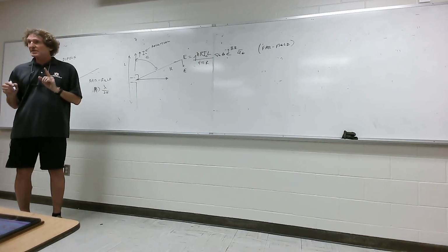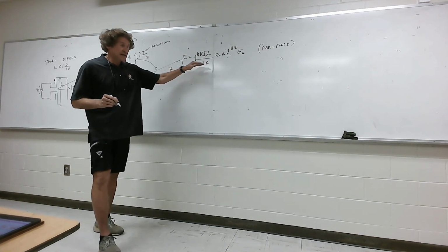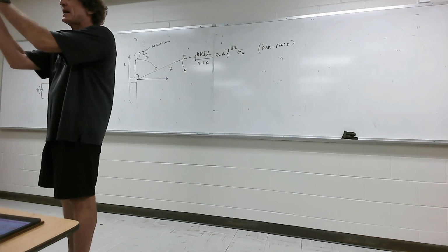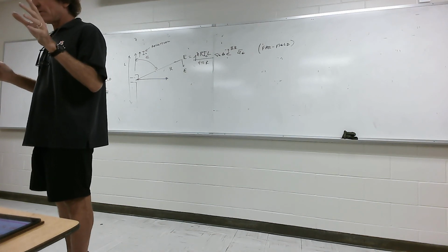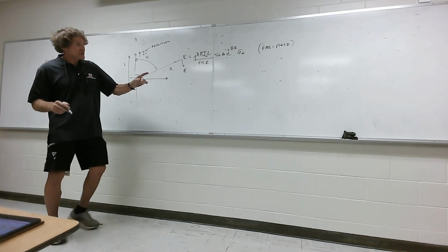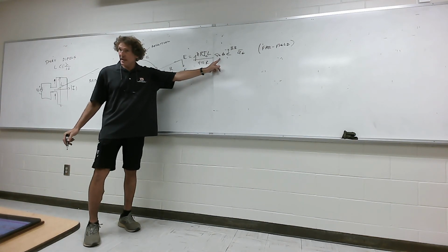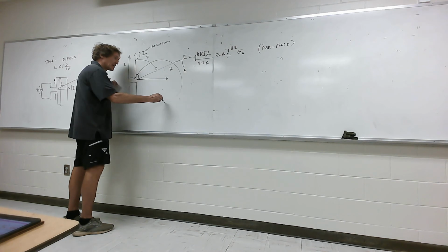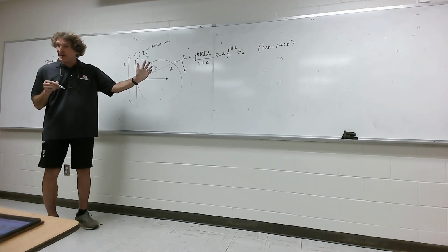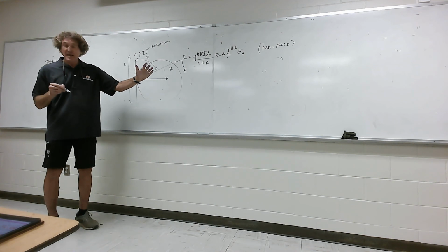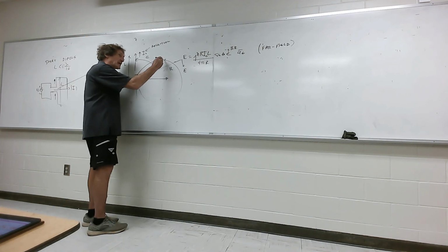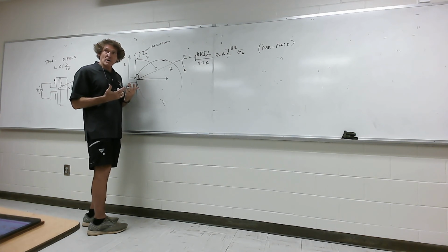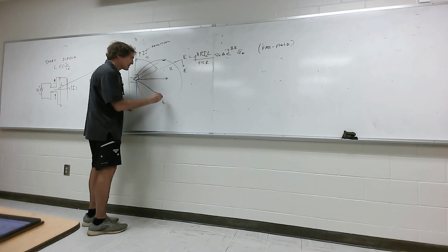Now, if you were to actually get the power density, how would I get the power density if this is a radiated field, anybody? One half the magnitude of that E field squared over eta. Y'all hear me? If I do that, you can see it's proportional to the sine squared, can't you? Just square that. Here's what it would actually look like. If I plotted that, this would be the power pattern. It'd be a sine squared pattern. Maximum value there. We'll get into this, but when we find where the half power points are, when the maximum value of the power at a given range goes down by 1/2, this is called the beam width. You probably heard beam width before.